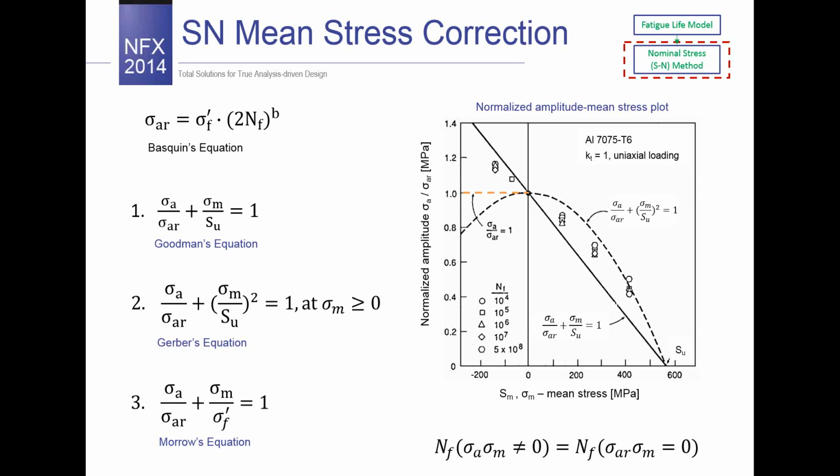But meanwhile, let's take a look at the picture. As I said, and I will repeat this again, for the case where stress reversal does not happen, so the loading has an amplitude and a mean stress, we have to use something called the Goodman diagram, for example. In this diagram, the mean value of the stress is drawn on the x-axis, and the amplitude is drawn on the y-axis. When the mean value is 0, we know that the stress limit is the same as the endurance limit. When the amplitude is 0, there is no cycle, and this is the same as the static loading condition. So the safe limit for tension is automatically the same as the ultimate stress for tension.